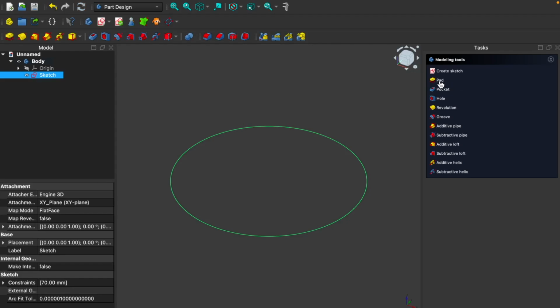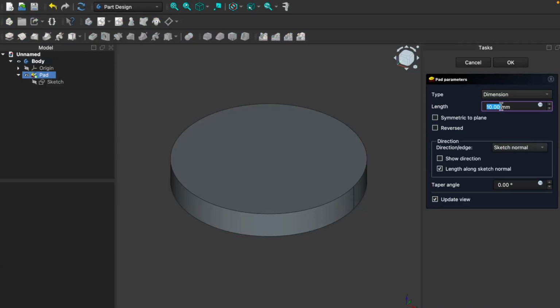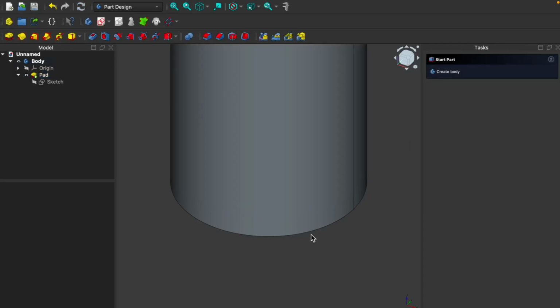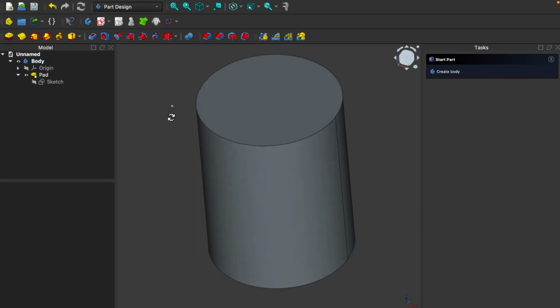And I'm gonna pad it out, like make this solid itself. And for the height, I made some measurements before we started, so I go with 90 millimeters, and that's the right size. Click OK. Press the fit-view shortcut on your keyboard to center the whole thing.